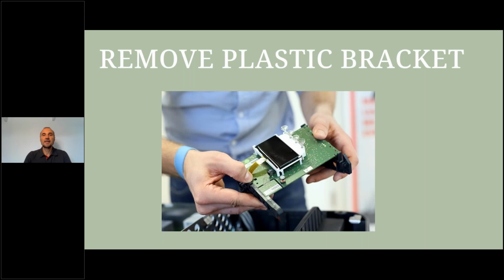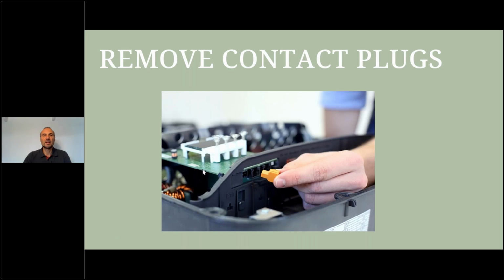This is the display card. When the display card has to be replaced as well, you can see that there is also a way. If I just go back to the other slide, if the display has a problem, you can also take off this display card here. The display card consists of 2 cards, and they are connected in the inverter.